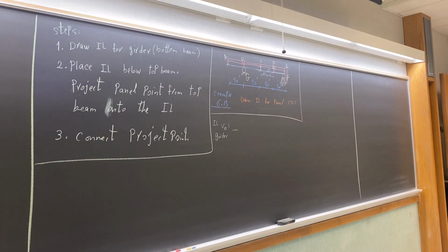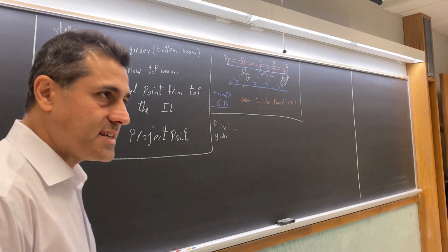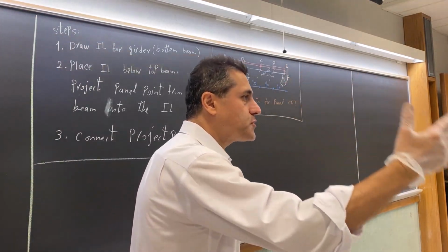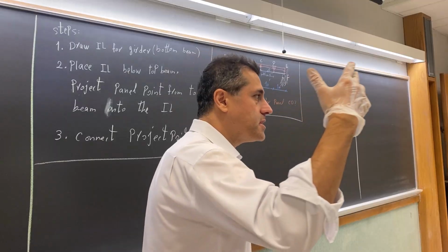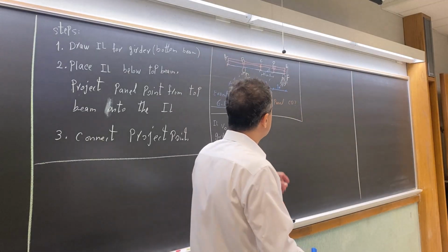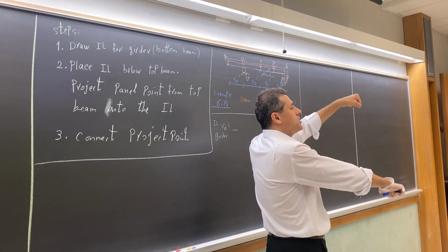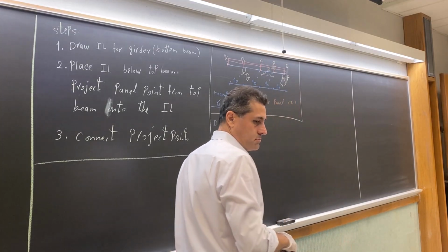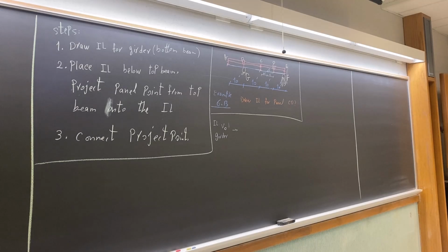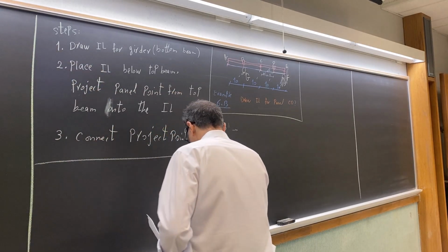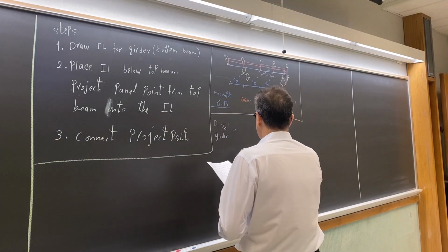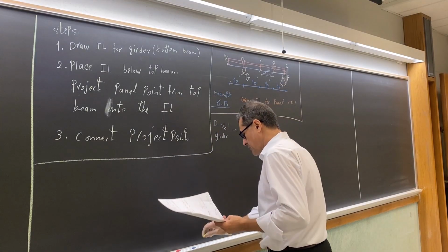Consider the unit deflection, consider the sign convention, remove the constraint, replace it with a proper joint, which is a shear hinge here, and then apply a unit displacement, etc. So I just write the final answer because you know the process. So this is the beam.